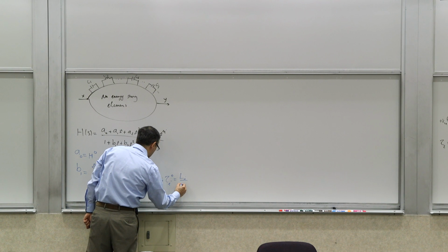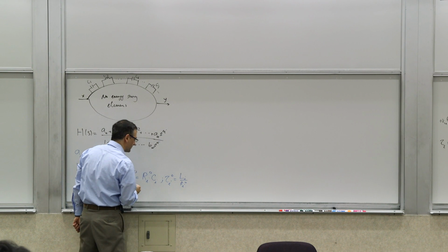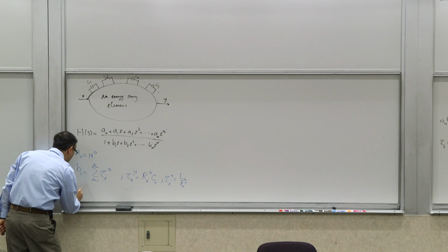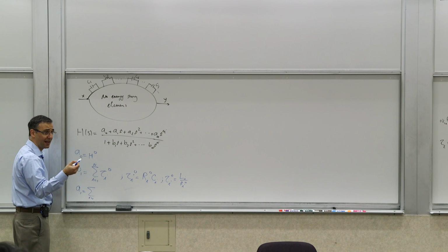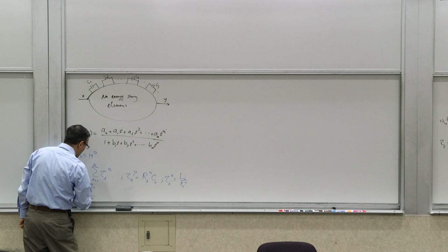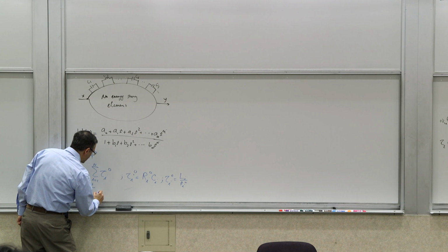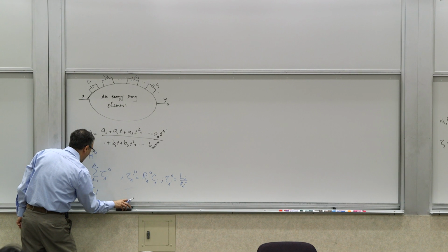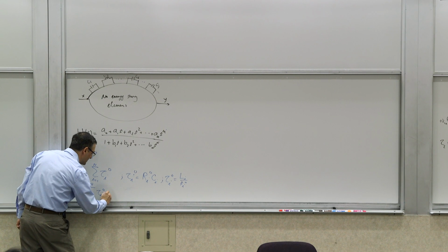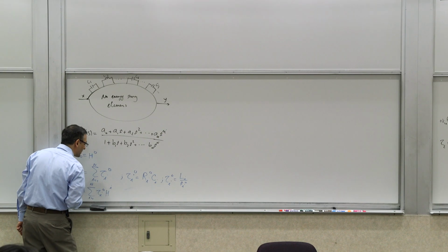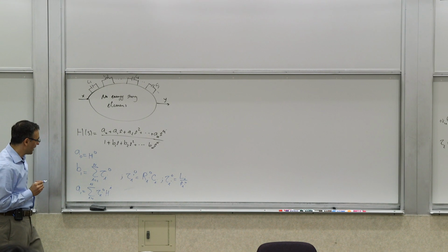or if you were dealing with an inductor, alternatively, tau_i0 was Li over R_i0, right? And then we had element a1, which we calculated to be exactly, these are all exact, and everything with the TTC is exact. The sum from 1 to n is basically tau_i0, the same zero value time constant, but scaled by what we call the first order transfer constants, hi.